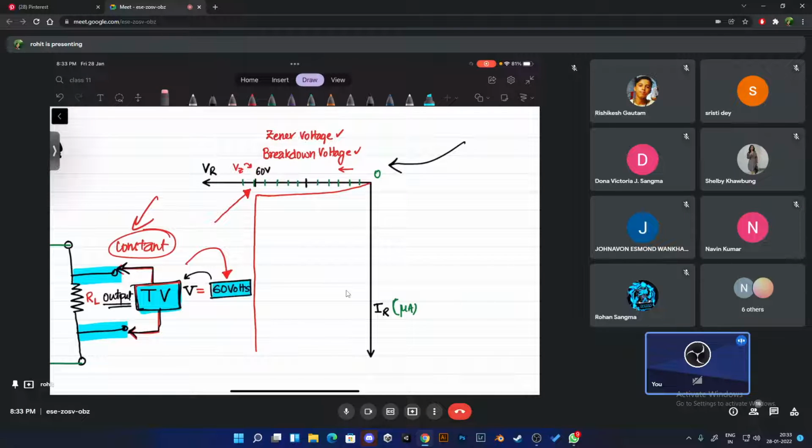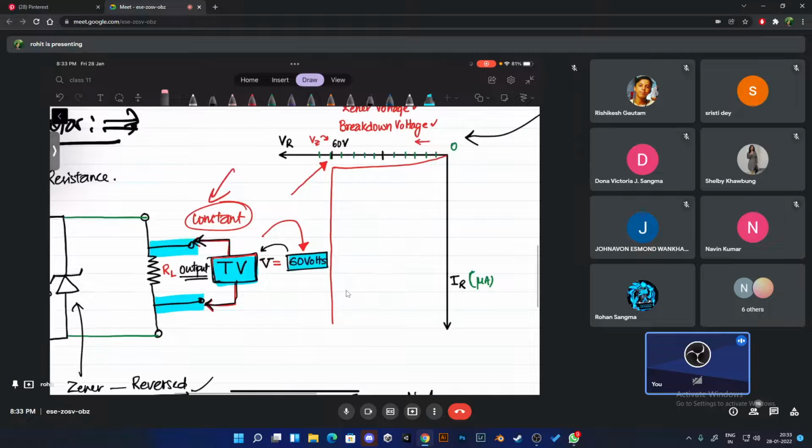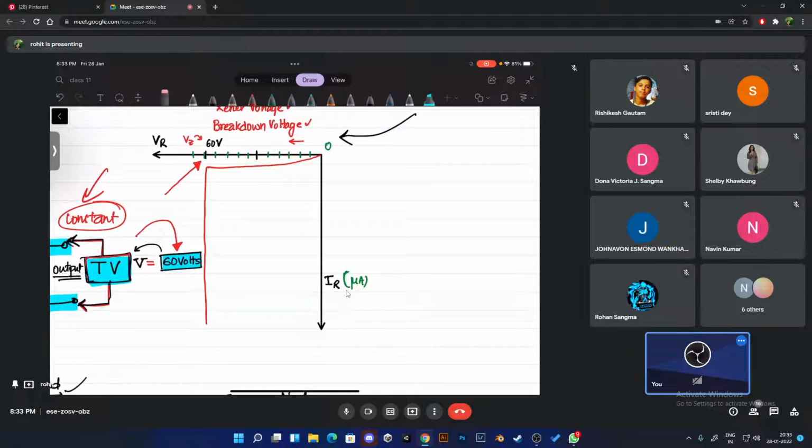If your TV needs 30, okay, I'm repeating again. If your TV needs 30, will I use the same zener diode or a different zener diode? Different. Use a different zener diode which will have breakdown at what voltage? 30. At 30 volts. Can you all understand what I said? Yes, sir. If your TV needs 30 volts, use this one. If your TV needs 60 volts, use this one. Okay, I think you understood. Don't worry, we are fine till now.